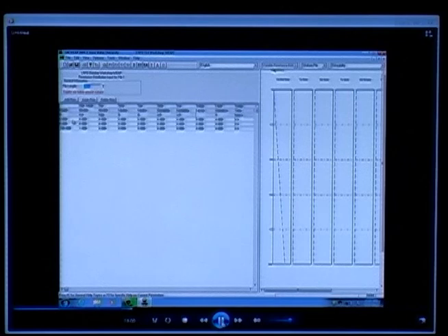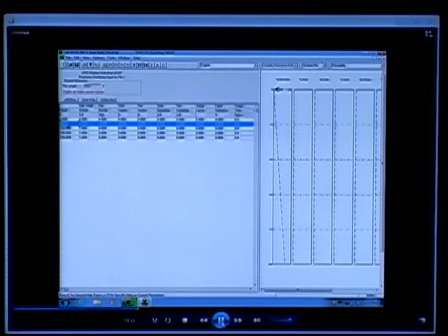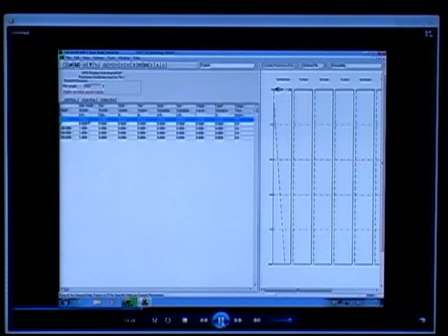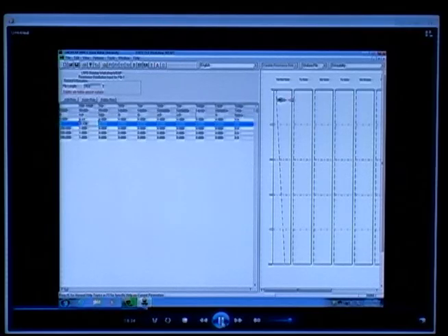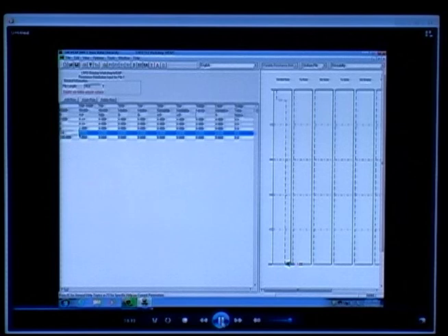This page allows you to input the geotechnical resistance distribution. The unit shaft resistance and toe resistance are selected from the Iowa design charts. In this example, the first layer for a depth of 6 feet is a soft silty clay with an average SPT N value of 4. The unit shaft resistance is determined to be 0.24 kips per square feet. The second layer down from 6 feet to 15 feet is a silty sand. The unit shaft resistance is determined to be 0.36 kips per square feet.